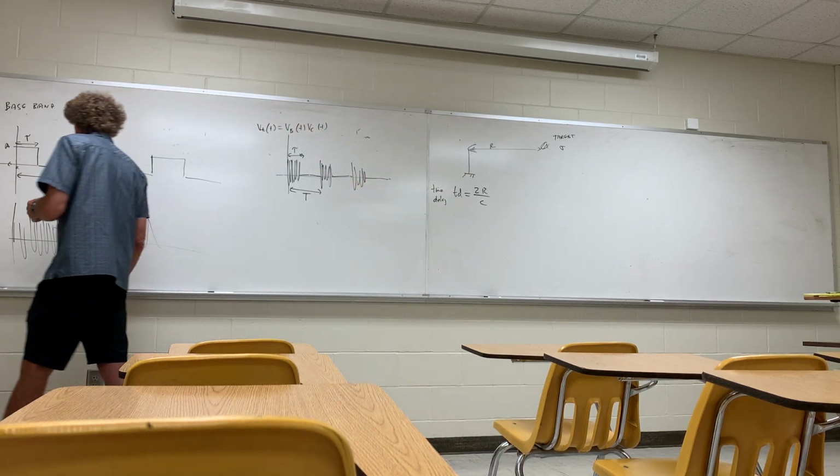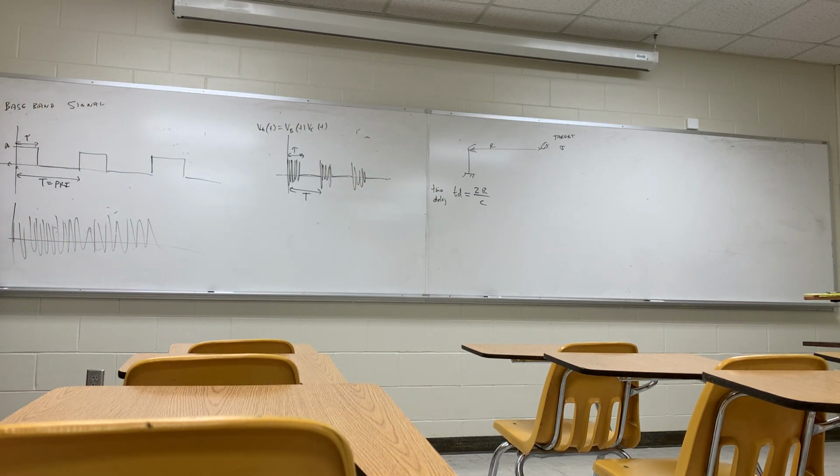Now, think with me over here. So here's my setup. I send a pulse at this point in time. The echo from that pulse has to come back before I send another pulse, or I don't know if this pulse or this pulse is responsible for the echo. Do you all follow me?